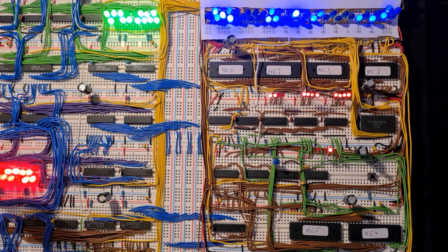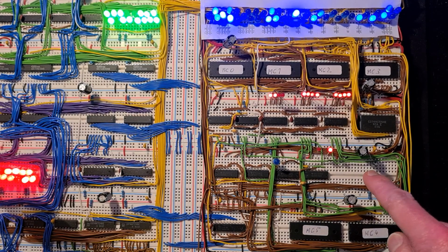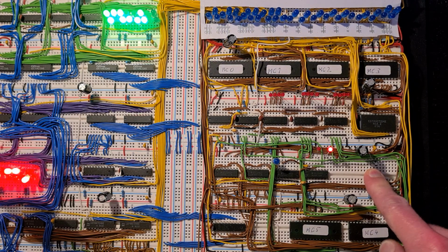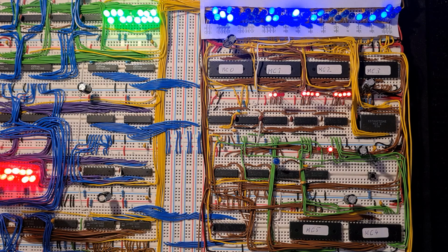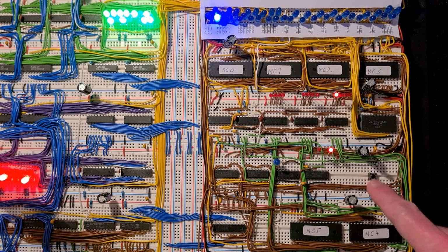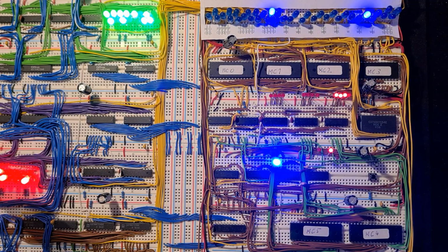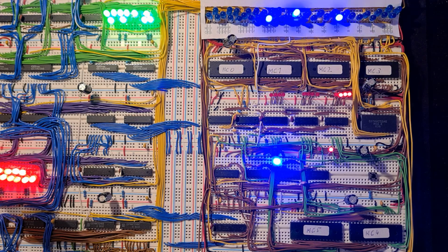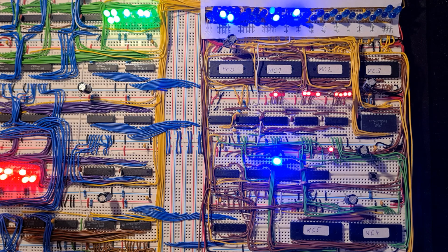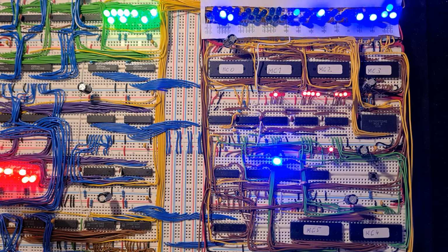In real life, a reset cycle looks like this. I hit the switch and yes, the microcode step counter goes to 0, and yeah, if you let the switch go, it runs fast. So there is a slow motion version of that video, and you can see the step counter slowly counting up from 0, and then as soon as it hits the first real instruction, the step counter goes wild, because all instructions have different positions and it switches from instruction to instruction and from address to address.